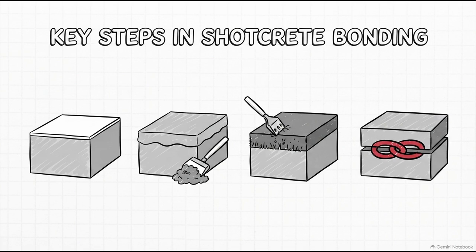And that brings us to our final takeaways for today. Remember, every single layer needs a sound receiving surface. Absolutely no trapped rebound or overspray. Always prep hardened joints according to the spec. And a major field rule, never assume yesterday's good shotcrete guarantees today's good bond. If you consistently apply this mindset, you are going to catch defects way before they get buried.